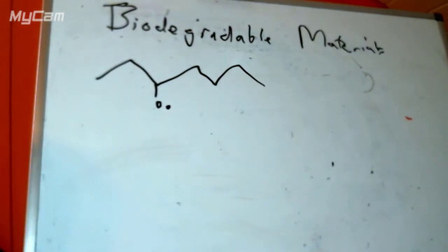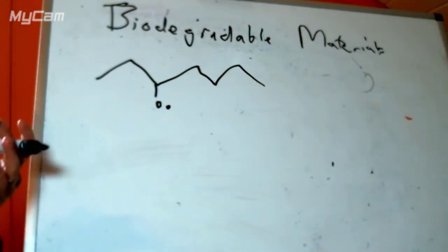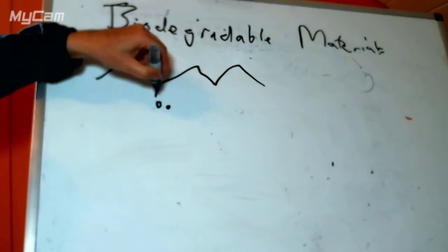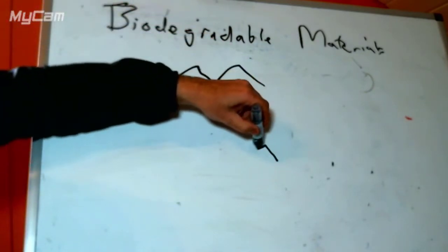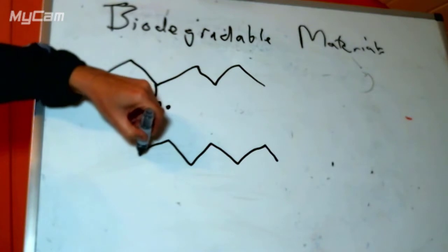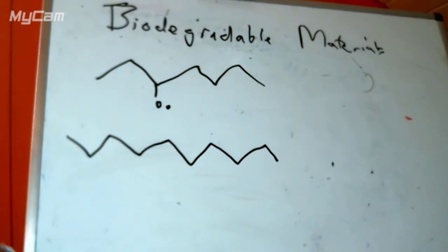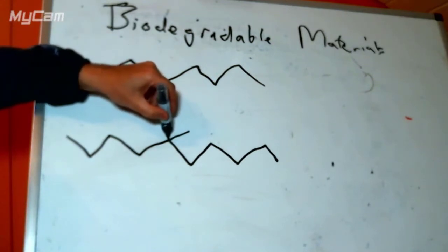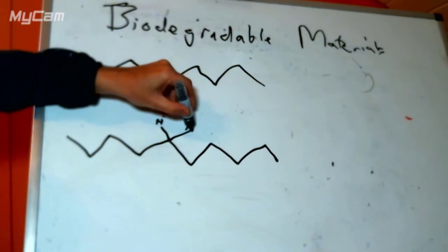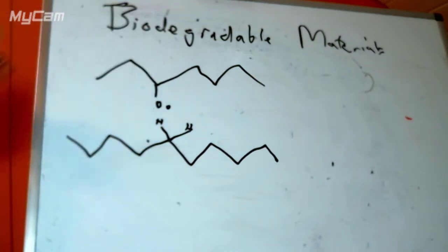Well, inside a polymer solid, there is no monomer for it to react with. There are no double bonds hanging around to react with our radical here. So what we've really got next door to it is another polymer chain. And the polymer chain has not very many bonds that it can react with. So it can either react with this hydrogen on the side, or it can react with this carbon. If it reacts with the carbon, it's cutting the chain shorter.